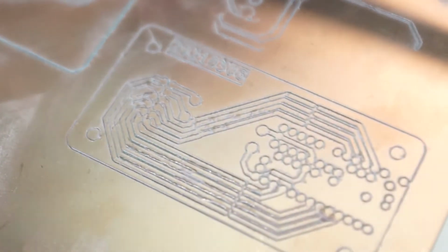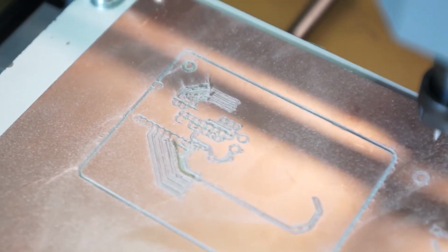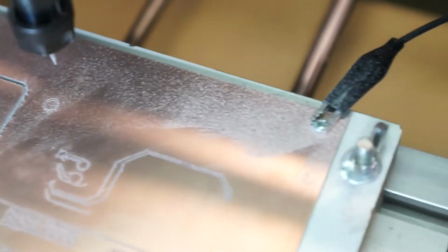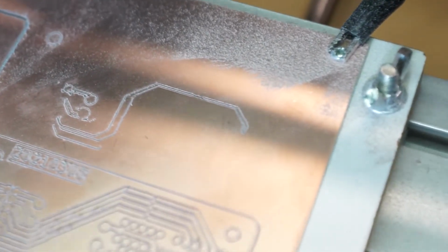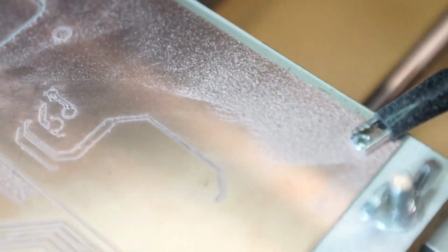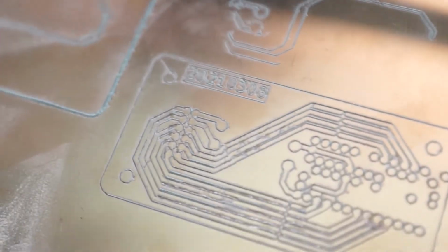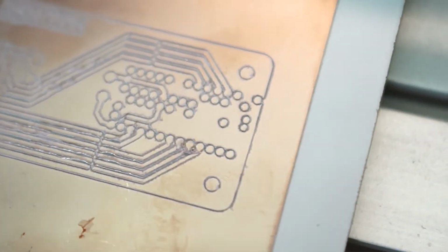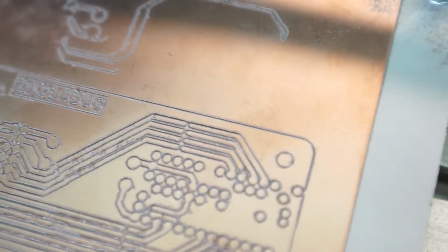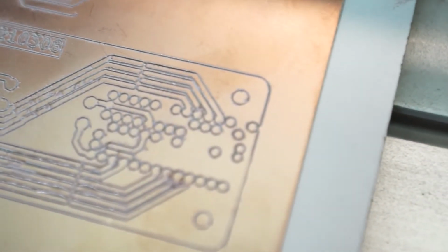Well, third time's the charm. First circuit board, no height map and mirrored. Second circuit board, trace being too narrow. As you can see, I have redesigned the circuit board. So what I've learned is that the traces can be fairly close together.